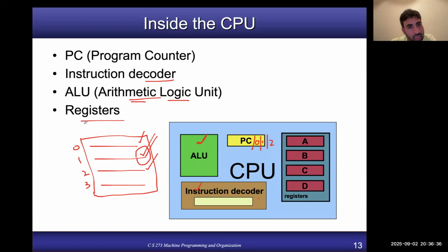Registers are the data holders. The data which you read from memory is placed in the registers, and the data which you write into the memory has a register as its source. The data which is fed into the ALU always comes from the register file. The combination of all the registers is known as the register file. So when you say, add registers R1 and R2, these two registers will be added.